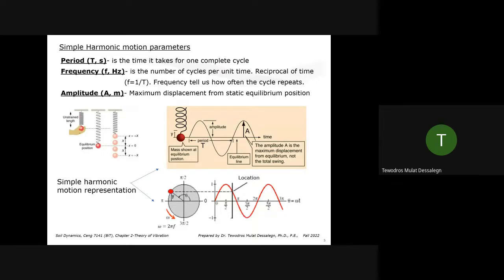Let's say you have a suspended spring, and without the mass, the spring alone, maybe this is its position. If you add some mass on it, there is a static displacement extending up to here. So this is, let's say, with the mass, the neutral position. Now give it a little input initially and let go. What happens is it oscillates back and forth about the neutral point, the static neutral point. So this is now vibrating. In the static case, it wasn't vibrating.